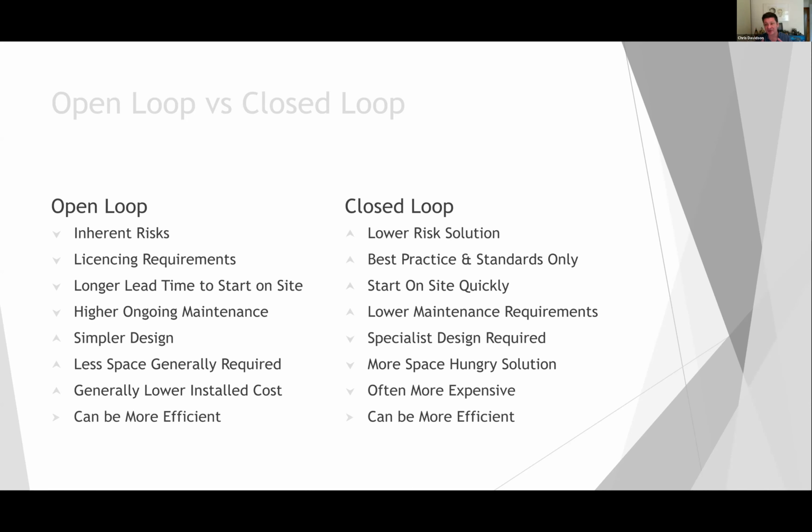There are differences in how they operate. The physics of the two are quite different in some ways. And that can mean that an open loop can be more efficient in some instances, and a closed loop can be more efficient in others. So let me give you an example to illustrate that. If you are looking at a heating only system, it is very likely that open loop will result in a more efficient solution than closed loop.